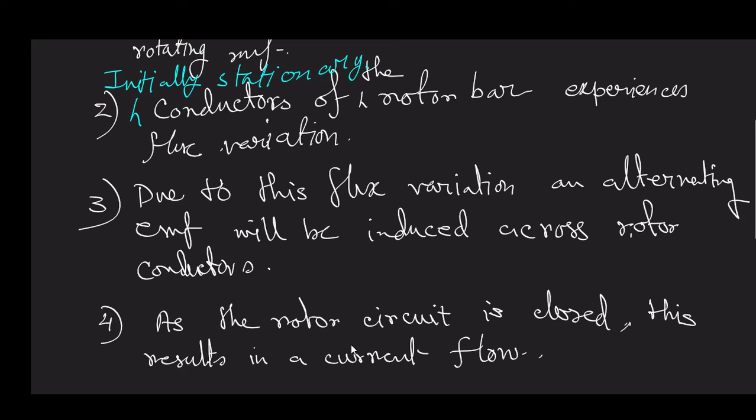In a DC machine, what we notice as back EMF is a dynamically induced EMF, and here what we are getting is an EMF induced due to magnetic field interaction. So this is not induced due to dynamic action.